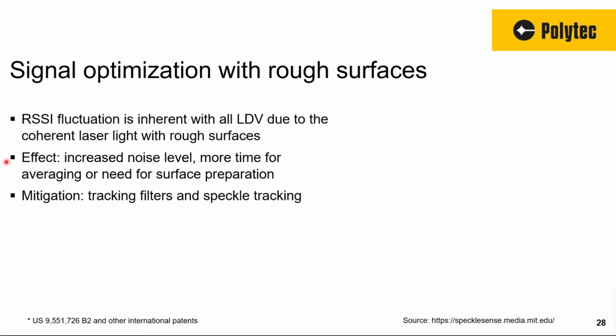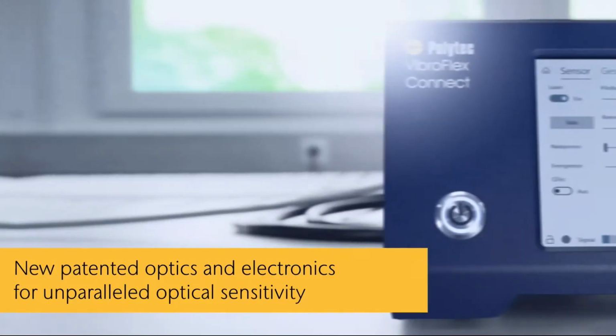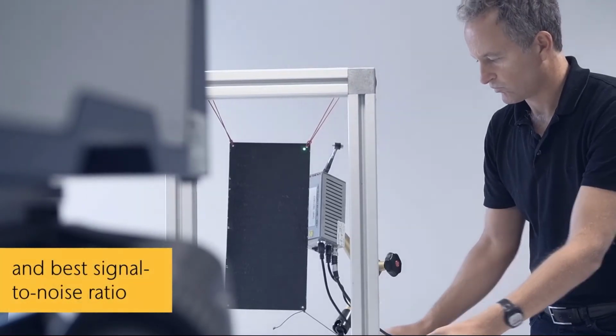But there's also a way to solve the effect. And this is the so-called multi-channel interferometer featuring diversity reception. We call it QTAC. That's a patented technology just introduced on the market. And we use the statistic fluctuation received from multiple detectors to combine it to a stable and continuous signal. So it's a combination of optics and electronics implemented in the Vibroflex system.